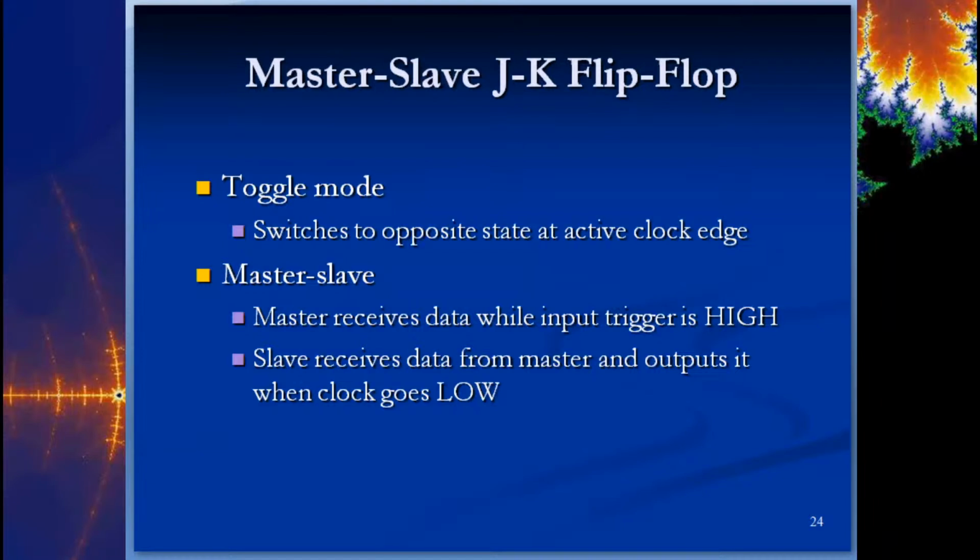So before, we talked about D flip-flops and SR flip-flops and what those look like, and we can construct them from cross-coupled NANDs and cross-coupled NORs. And so we're going to take the idea of the SR flip-flop and use it in a little bit different way that will ultimately allow us to create counters. This is a very important thing that was figured out to get us into a toggle mode where we can always just go between 0 and 1 and 0 and 1. That's where most of the JK flip-flop stuff is used.